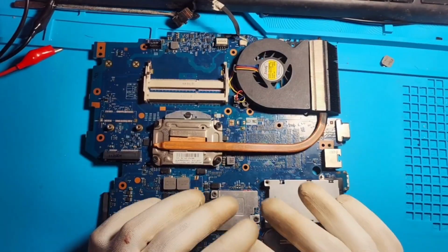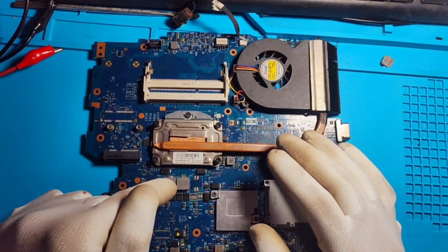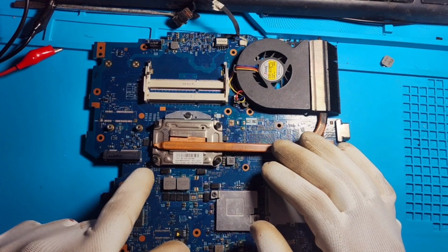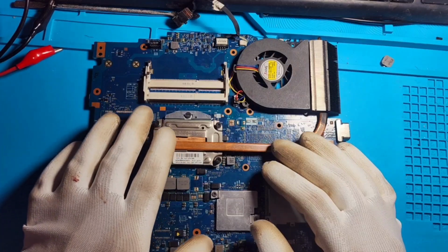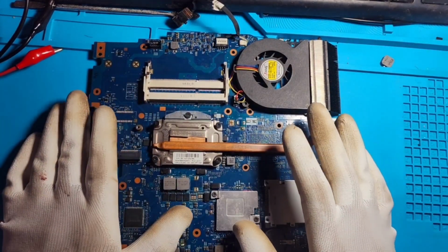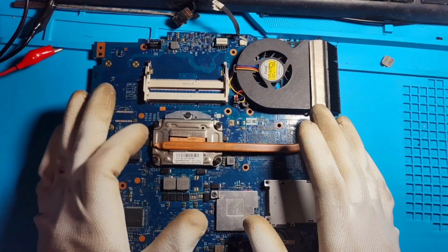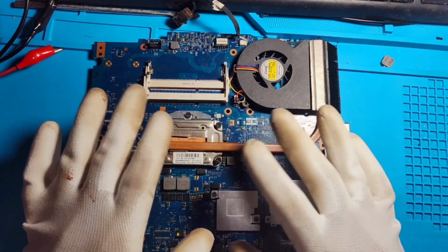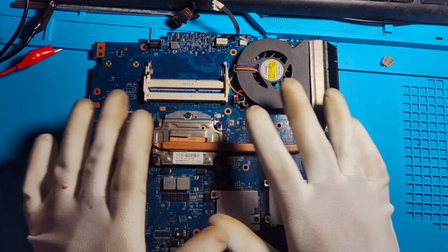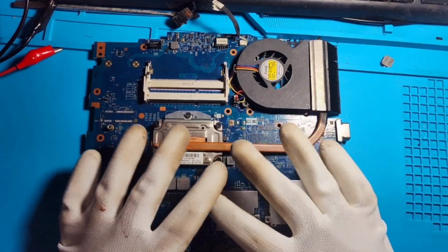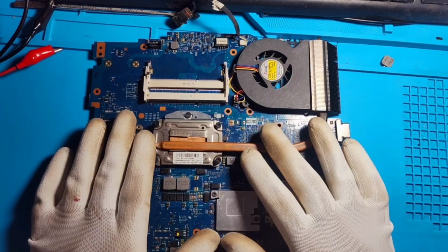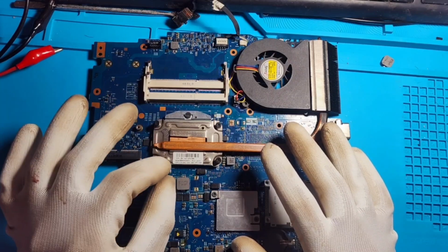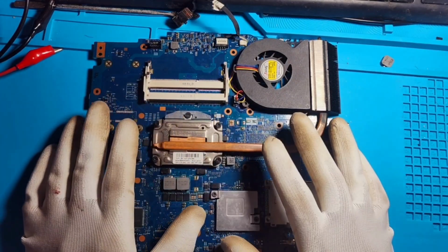Before moving on to replacing the regulator IC of the CPU, the MOSFETs, and the capacitor, I have checked the entire motherboard based on the sleep states such as S3 signals, S4 signals, and also the run power and suspend power, and checked everywhere in the motherboard whether everything is fine. Up to now I have checked all the power planes in this motherboard and they are working good, and I have checked the power good from each of the regulators and they are high and working okay, so there is no problem.